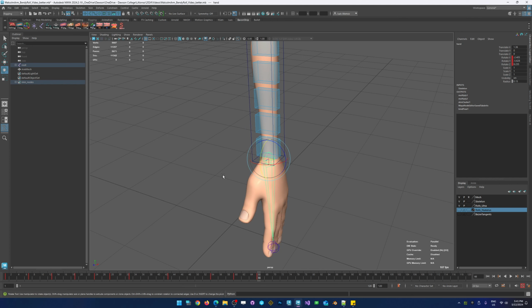So if you haven't looked at the videos on the basics for rotation: if I tell you that a position and a scale have independent components, meaning the X value and the Y value on a position are completely independent of each other, you're probably going to go, well, yeah, no kidding. But then if I told you that's not the case for rotation when Euler is involved, if you didn't know that, I would strongly suggest looking at the videos related to rotation and gimbal in the Rigonomicon's section under basics, because that is a fundamental thing that we need to keep in mind while we're doing this.